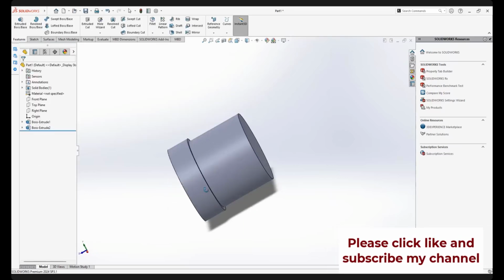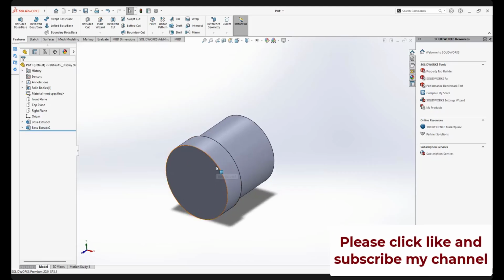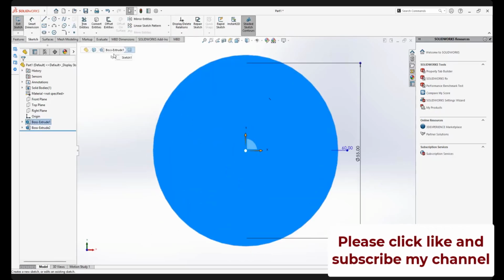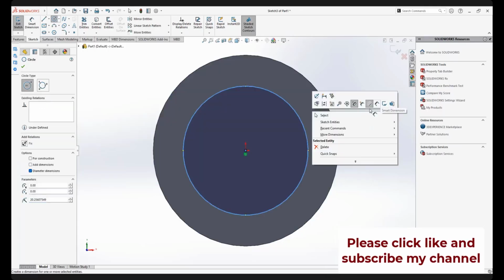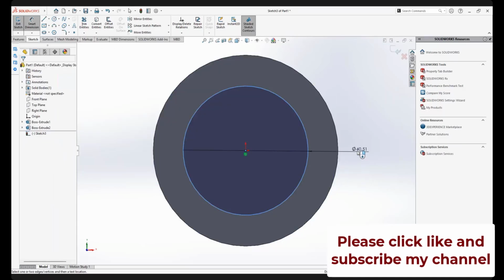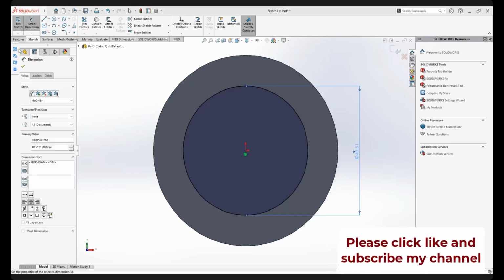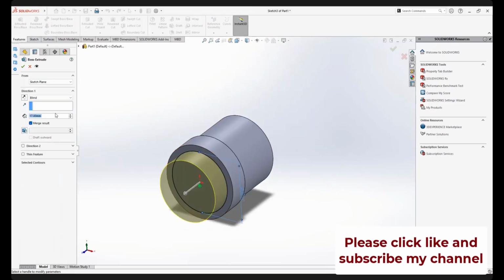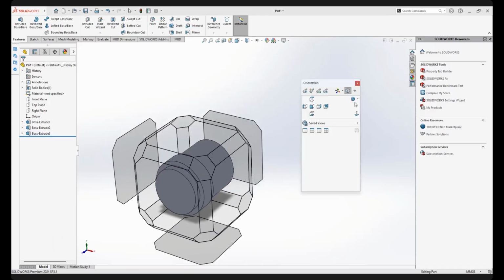So how do things go, right? Then we have the nozzle there. Diameter 50. Here, sketch the nozzle there, the front circle, diameter 50. And we extrude about 8. Make sure the direction is this way and the distance is 8. So I have this thing. Okay, we go for standard view.